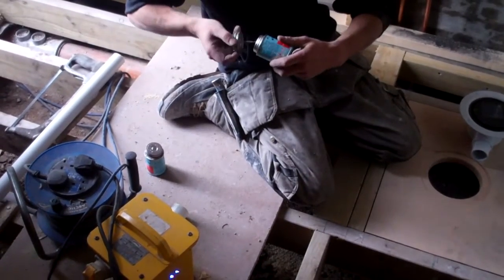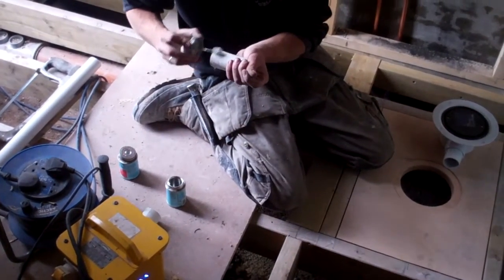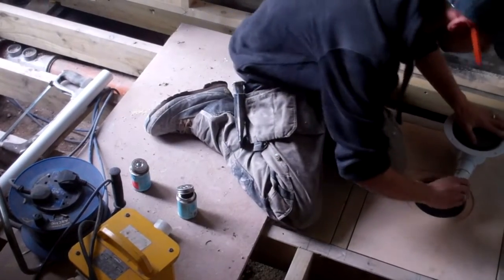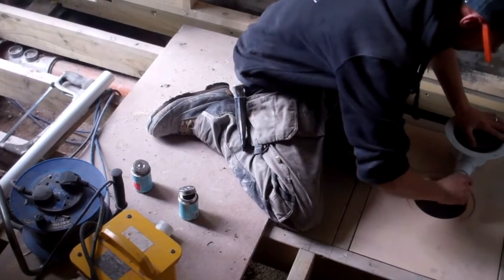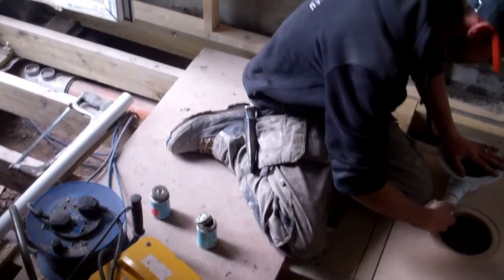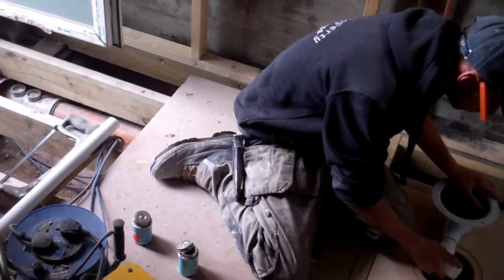We can now fit the supplied waste gully into the waste support. Pipework is normally solvent welded for a really secure connection. Joints can be loose fitted to start with, but don't forget to solvent weld them before fitting the tray. For plastic waste pipes, the slope to fall should be a minimum 2%.